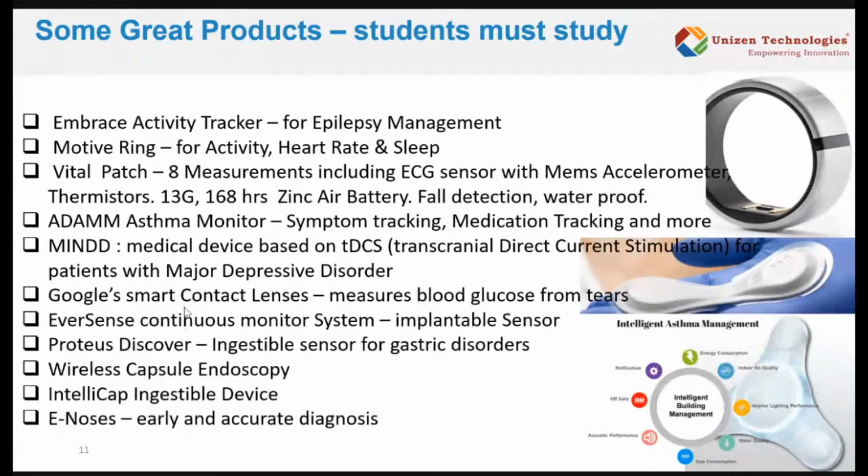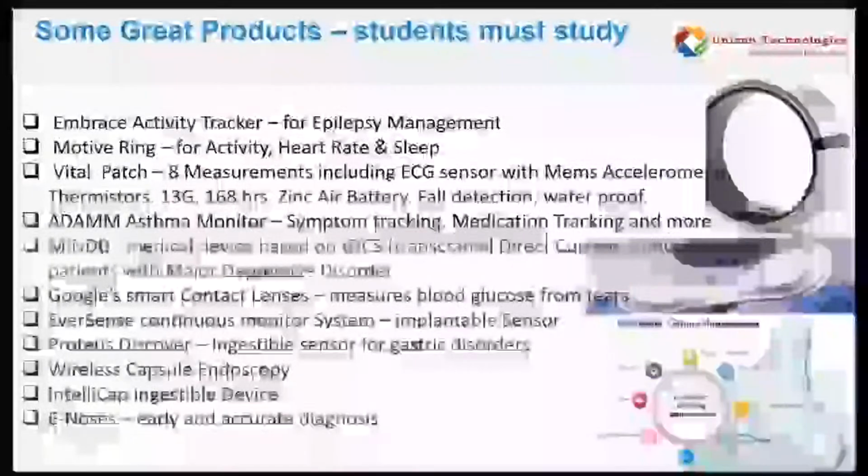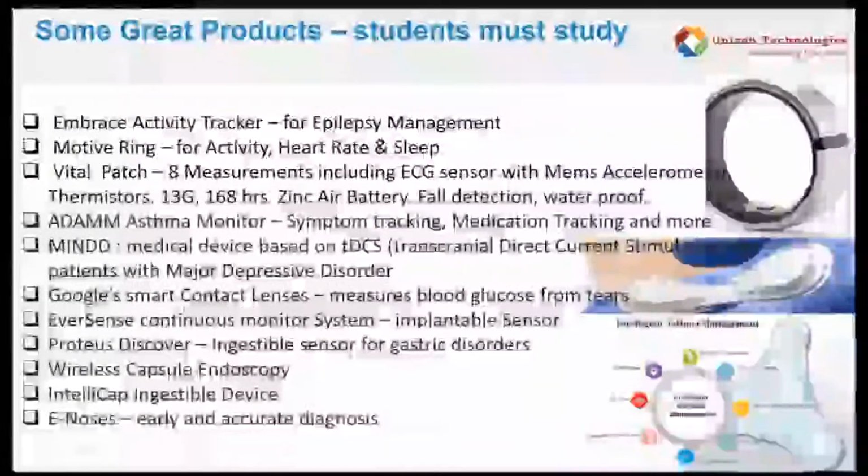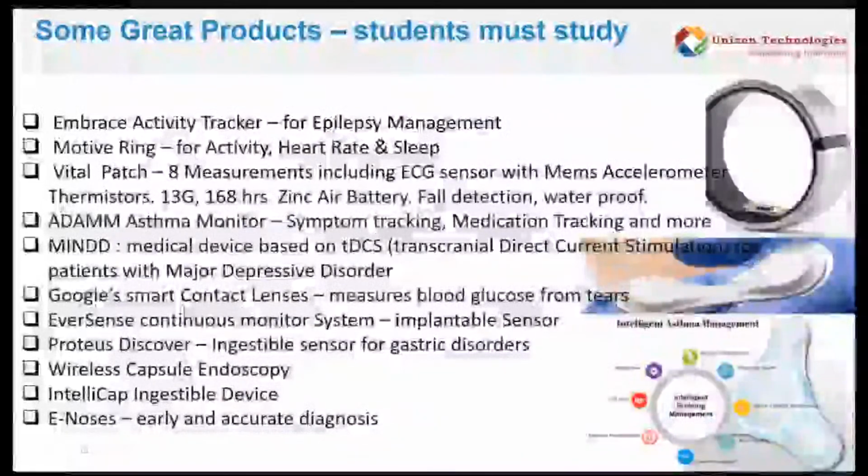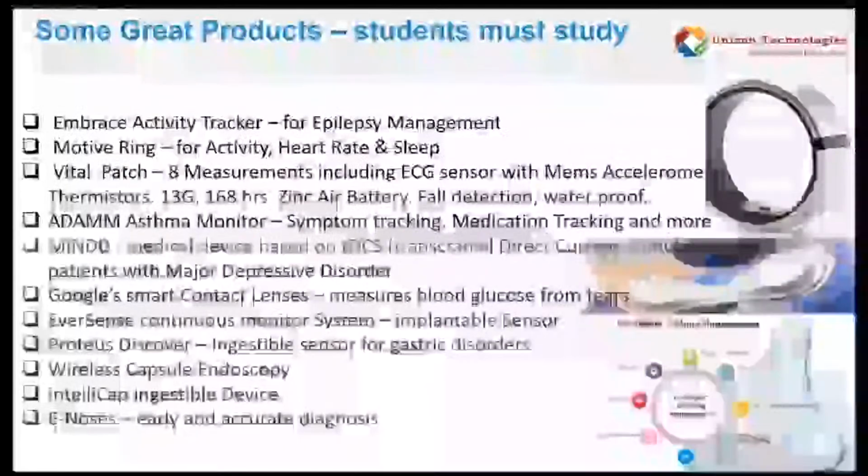So you can calculate the type of current it should draw when it is on and off and other things. In this particular implementation, every 15 minutes, it can be configured, it will check the temperature, transmit over Bluetooth, and then go to sleep. During sleep, it only consumes a couple of nanoamperes of power. And once it is on, it comes to milliamperes, but only for a very short period, and then again goes to sleep. The cost is just about rupees 150 in 1,000 plus quantity.